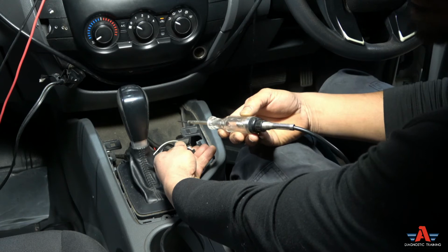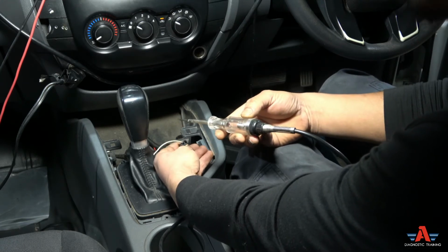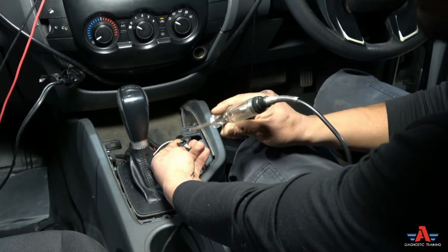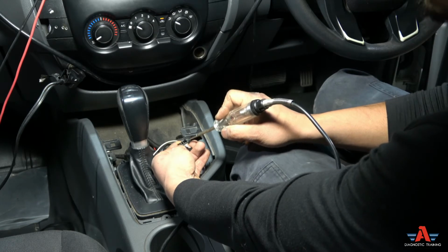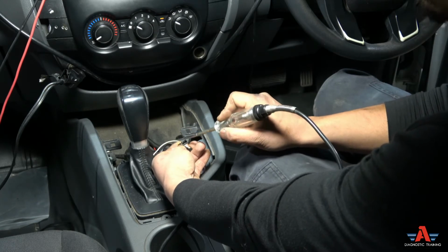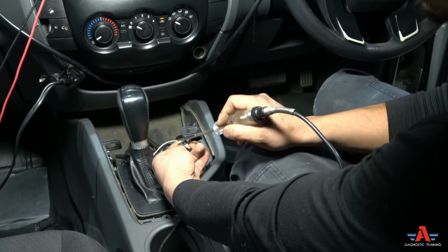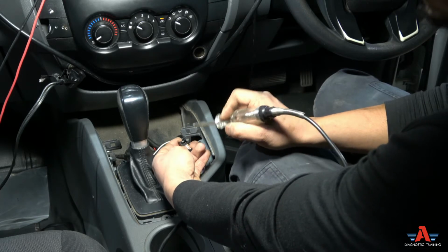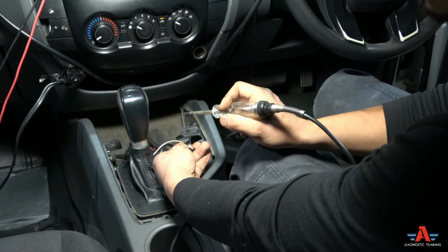If you want to know how the reference circuit works, go watch all my fundamental videos. There I explain everything that happens inside the computer, and why you don't have the test light lighting up here with your reference voltage. Obviously, if there was a 12 volt reference voltage, the test light is not going to light up because it's too heavy. You're going to have a lot of voltage drop, so the test light does not get that straight 12 volt. That's why the test light is not lighting up.